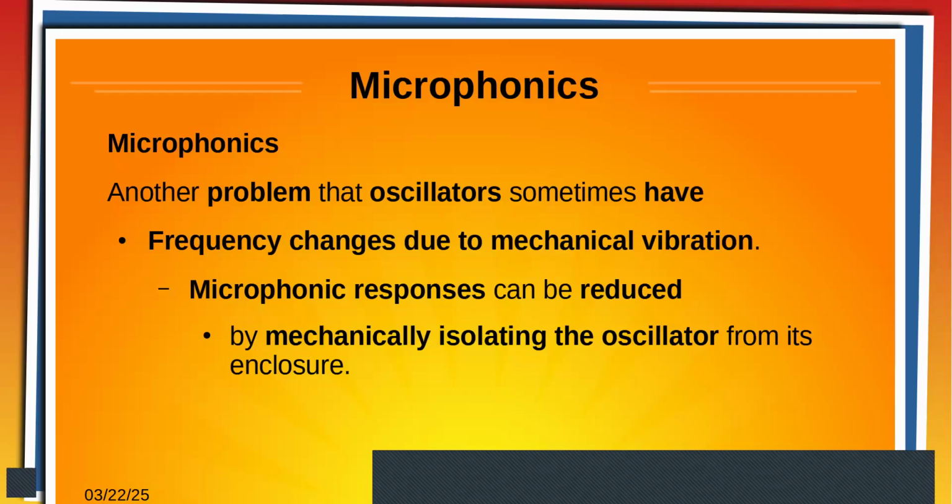If it was a tunable capacitor with plates, that could be affected too. So mechanical vibrations can have some effect on the frequency of the oscillator. To combat that, if it's a problem, you have to physically isolate it so that you reduce the vibration.